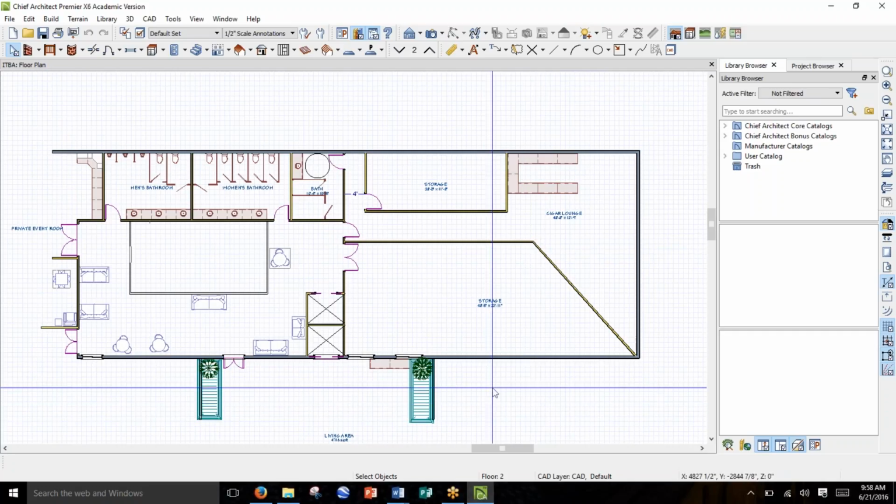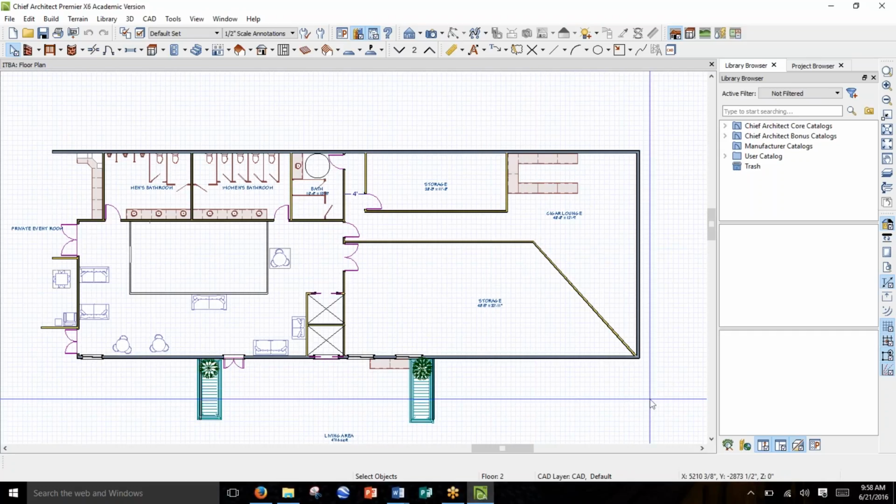But yeah, no, I like this solution. I like that the bathrooms are by each other, and even I know that that's fine. Let's see, 2, 4, 6, 8. Yeah, you're fine with that because it can't be a dead-end hallway of more than, I think, 20 feet, but you're going to get to your door before you get to the actual dead end. So you'll be fine with that. Wouldn't have to change it.